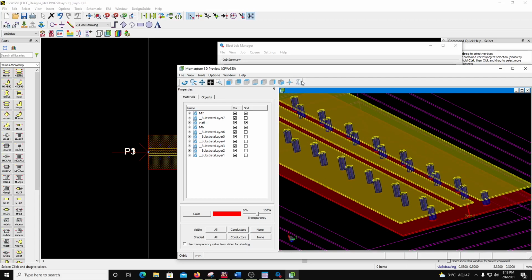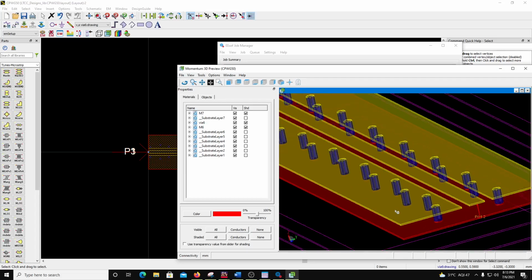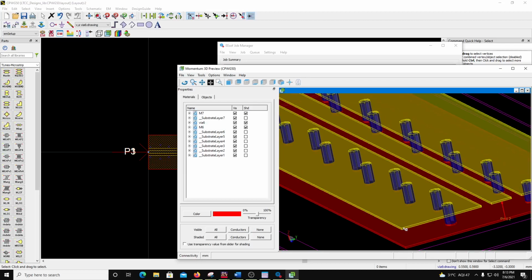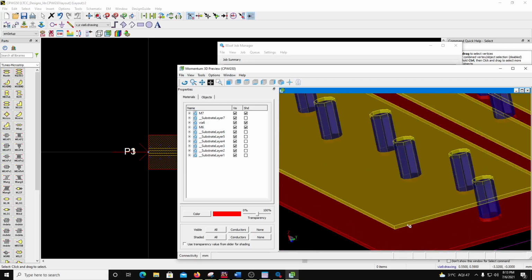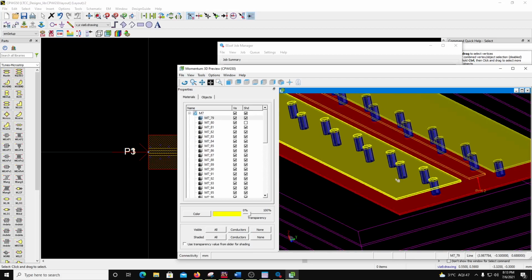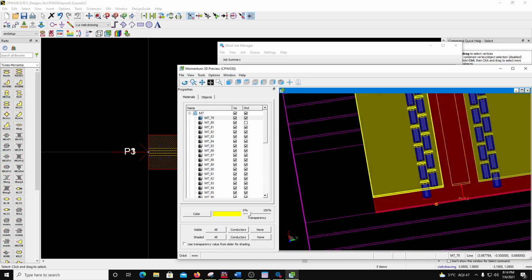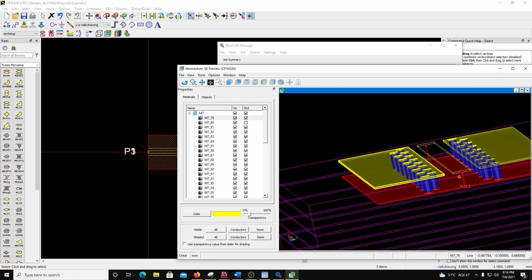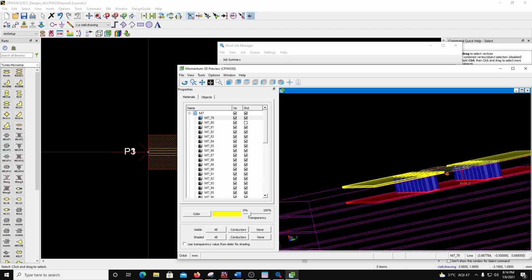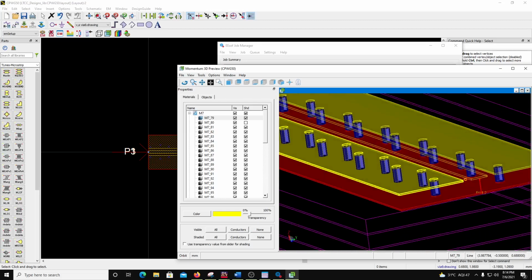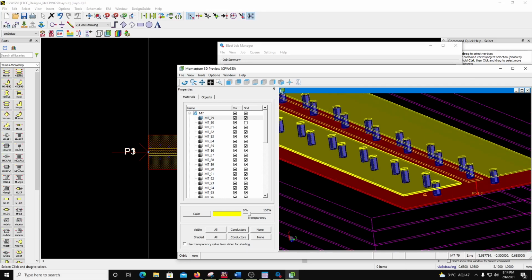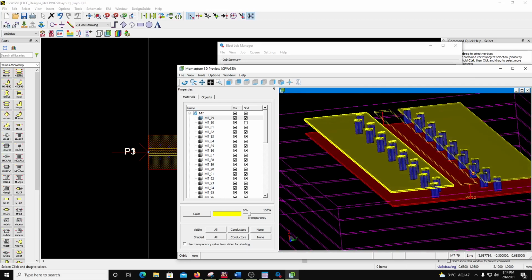Now, as far as connectivity is concerned, all the grounds will show up if I select this one. Yeah. So you see, this solid connectivity tool is saying that the center line is not connected to the ground anywhere because it is transparent, while all that is translucent is basically one piece electrically.